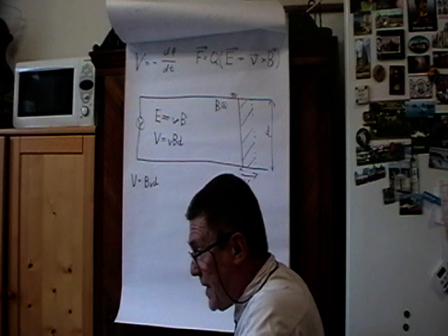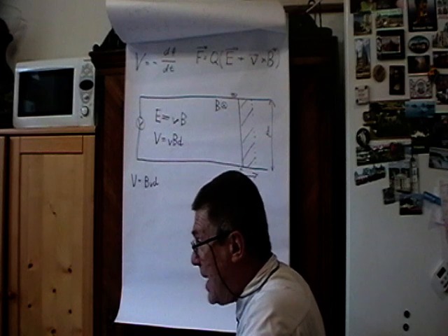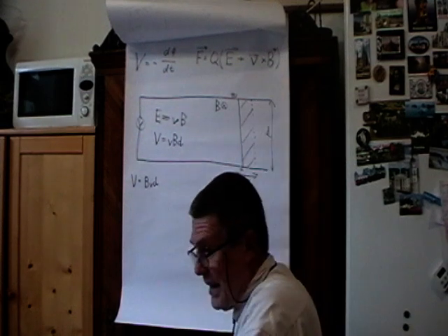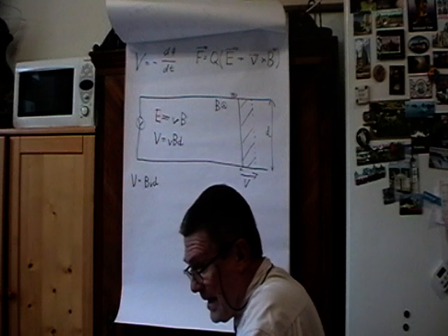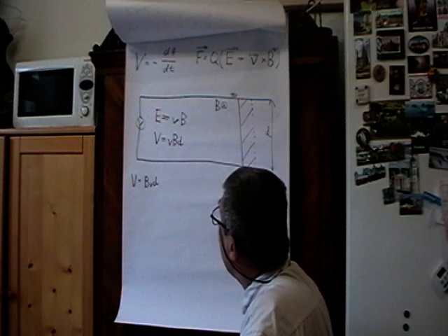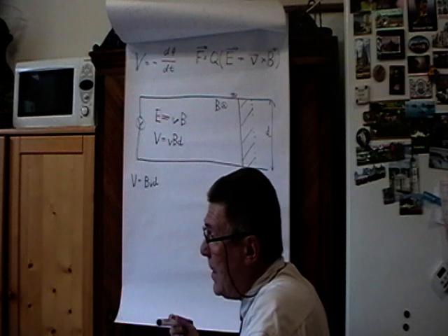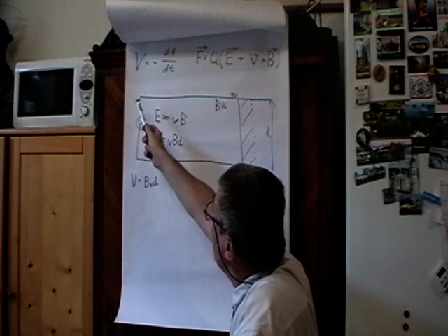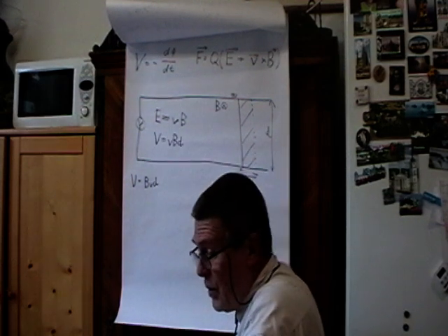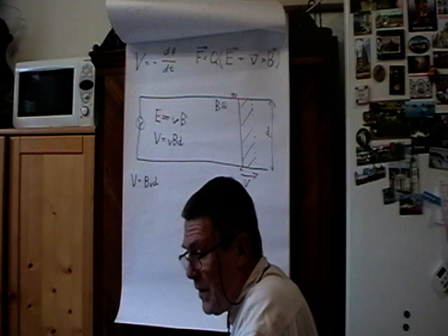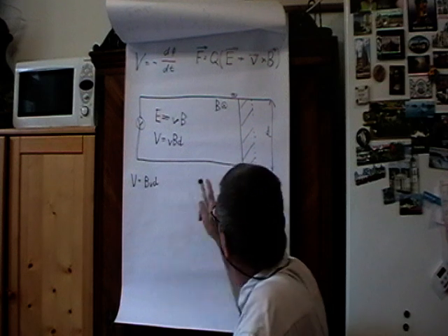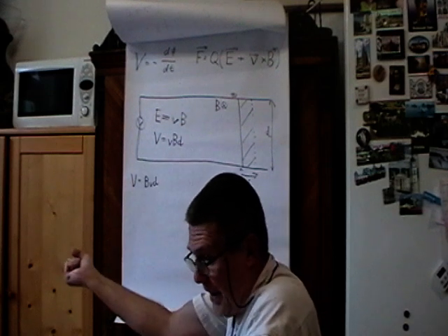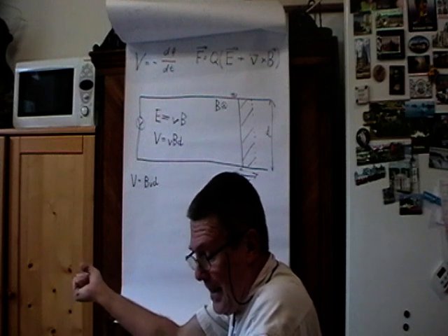So both laws gave us the same result, but we now know, using the Lorentz equation for force, that we only obtain induced voltage within the stick. The non-moving parts, like the voltmeter or those rails, do not affect it. In fact, the induced voltage would be there even if there are no rails. If I just carry a stick through a magnetic field, I would obtain an induced voltage on it.